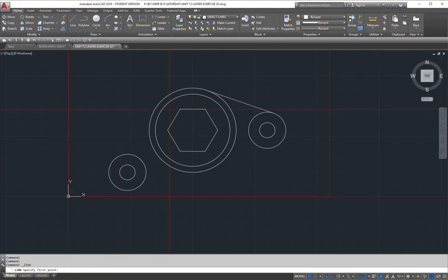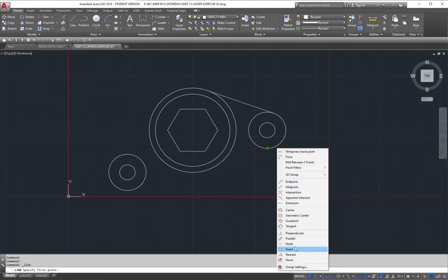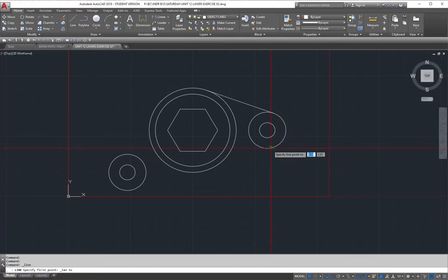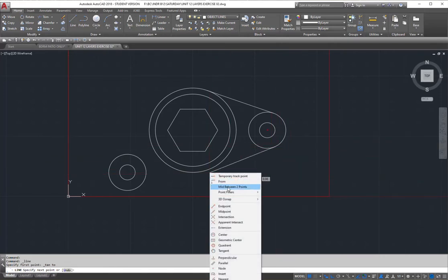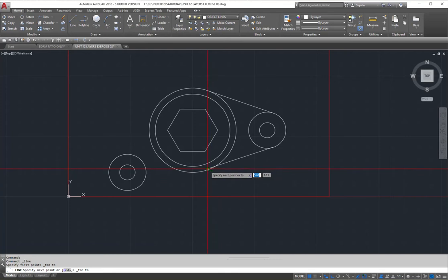So another line right here, go tangent point. Remember, you can also set those snaps under your settings. Okay, right here under the grid and snap mode. So I'm going to go press and hold. I have the tangent right here, there, enter.